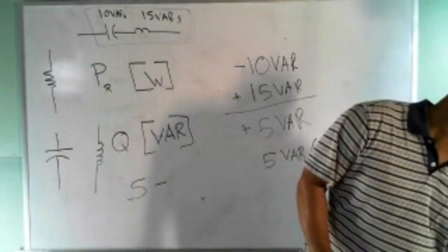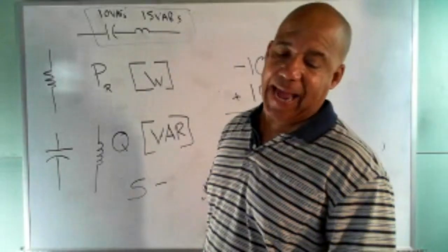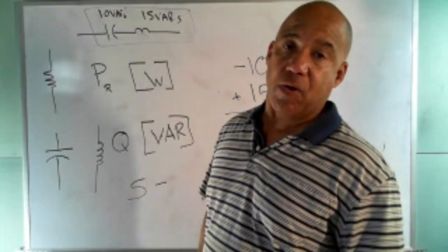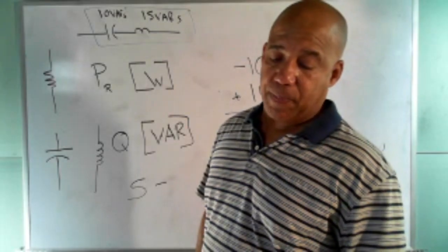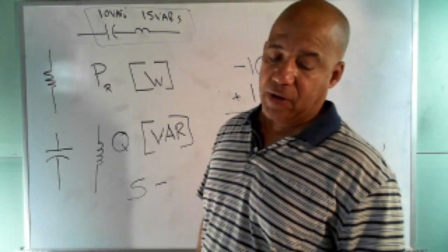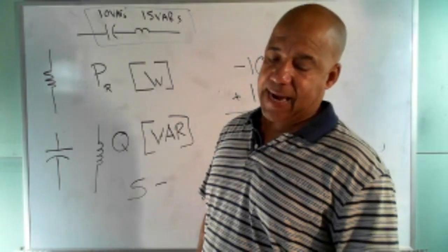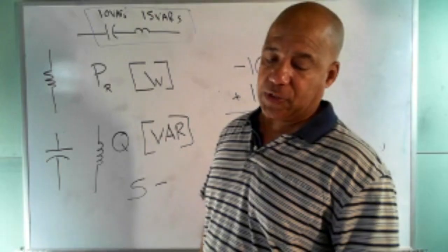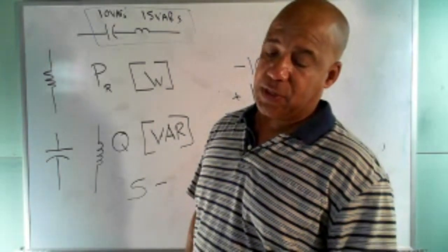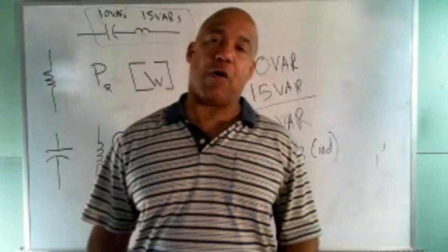Back to the sheet. So let me read what it says for reactive power or imaginary power. It's also called wattless power. It is the power value obtained by multiplying the effective or RMS value of the current times the RMS value of the voltage times the sine of the angular phase difference between the voltage and the current. Reactive power is not dissipated as heat. It is returned to the generating system. So we've already talked about that, the fact that reactive power is borrowed power.